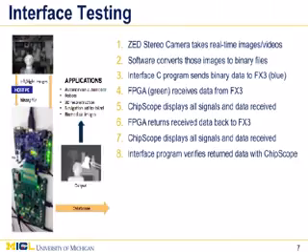This figure shows the ChipScope result for stream out. Flag C and flag D become active whenever FPGA receives the data from FX3, and output enable and read SLOE signals respond correctly along with the data received. This figure shows the ChipScope result for stream in. Flag A and flag B become active whenever FX3 receives the data from FPGA, and write SLWR is active, and other signals including address and data respond correctly.